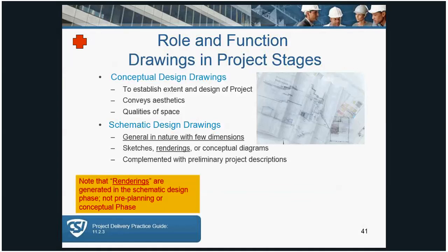When you get into schematic drawings, they'll start showing some dimensions in a little bit more detail. This is the phase that renderings are typically produced. A rendering cannot be generated until the elevations and the character of the building is established. This is the phase in which preliminary project descriptions are prepared rather than outline specs. Schematic design phase, you're doing preliminary project description.